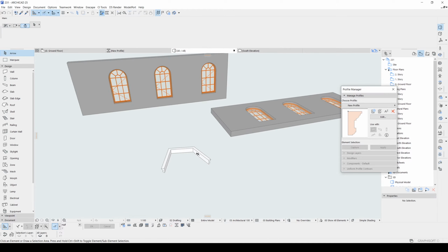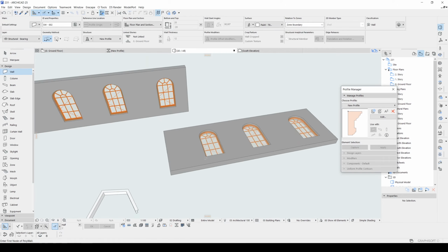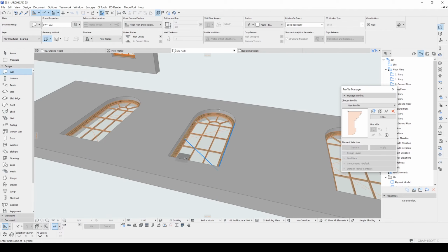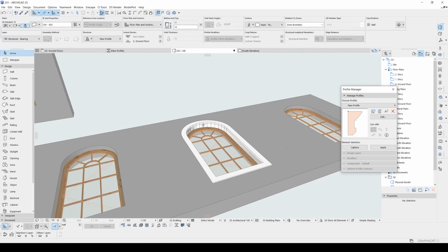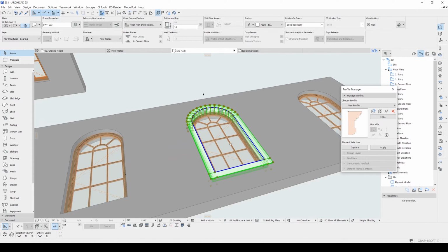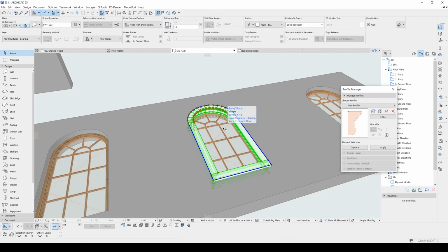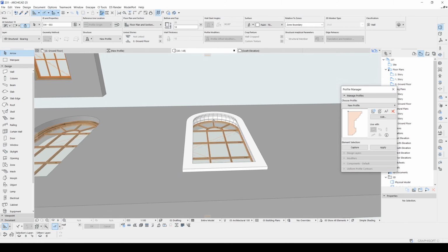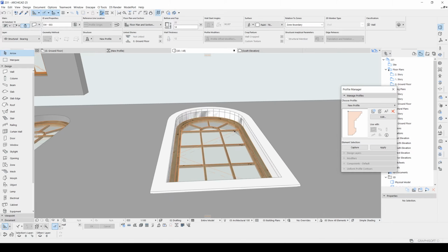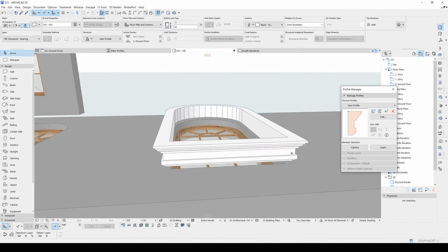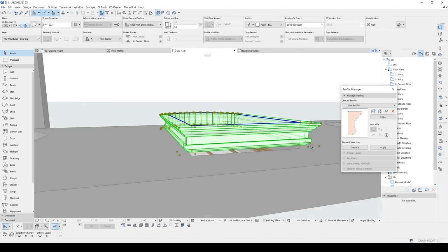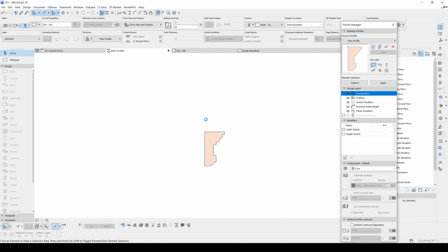Once we have done that, we can use our sweep onto this window. Let's try, hit the space. There you go. It works. Now let's select all of our sweep and change its direction. You can hit the P, but its direction is wrong. Let's change it, rotate it from the profile.